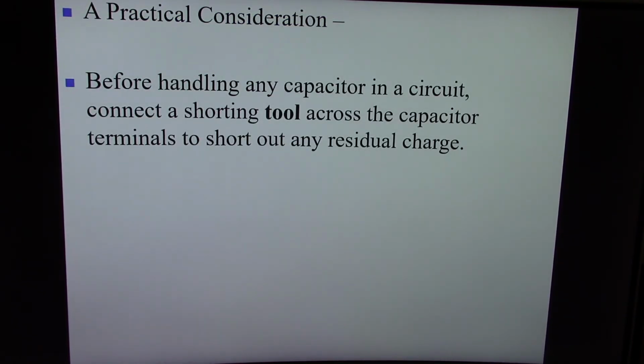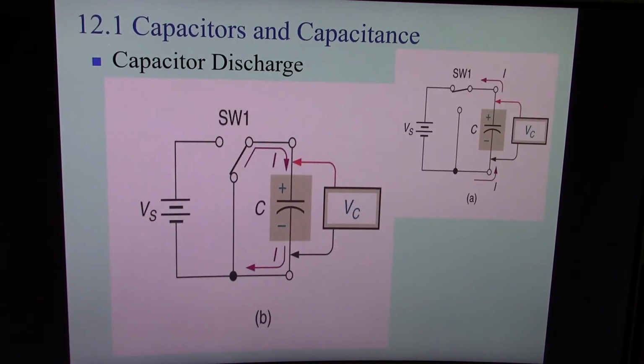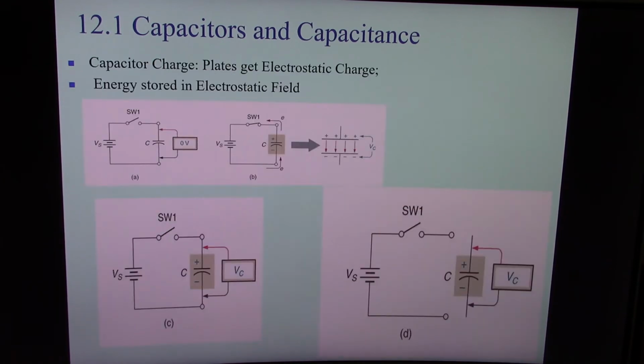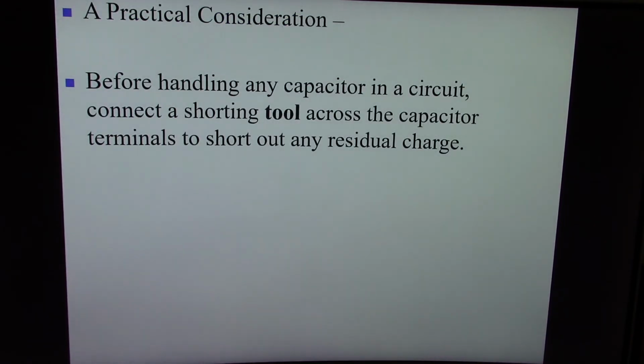So, going back to that previous slide, one thing to remember is that before a person handles any capacitors like these devices, or works with them in a circuit, I'll show you a few later on, you must make sure that you discharge it. You can discharge it by just connecting a tool across the terminals. Not. Okay? You don't do that.